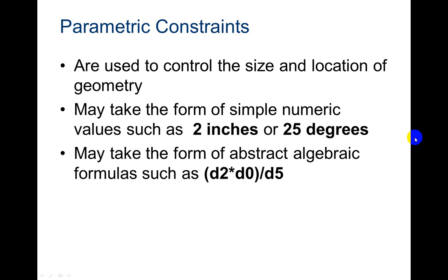All right, in this video, I'm going to go over parametric constraints. You've already been using them to some degree, but I'm going to show you how to go that next step and use parametric equations. So parametric constraints are used to control the size and location of the geometry.